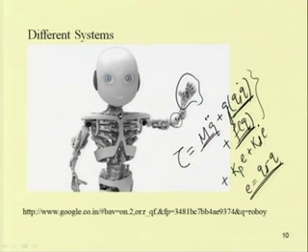So, error is q desired minus q actual, and q is the joint variable. M is the mass matrix. Taking all this into account, one can write the dynamic equation, and after getting the dynamic equation, one can check whether the system vibrates or not by solving this equation of motion.